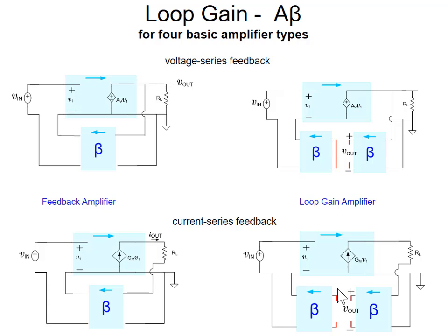We have a whole bunch of different feedback structures. So I'm going to show the terminations that we would have for breaking the loops with the different types of structures. So the one here is the voltage series feedback. You can sample the voltage and carry it back in series with the input. And here's the termination that we have.